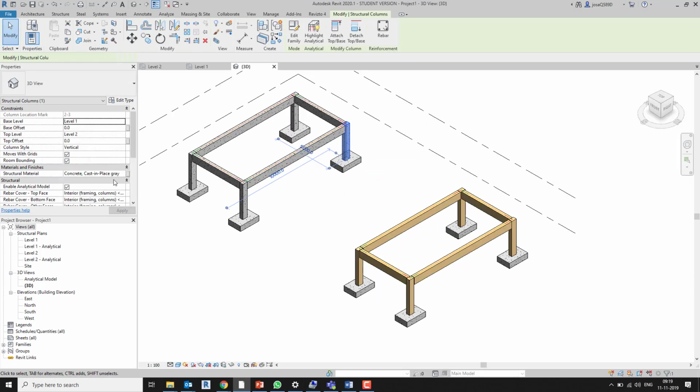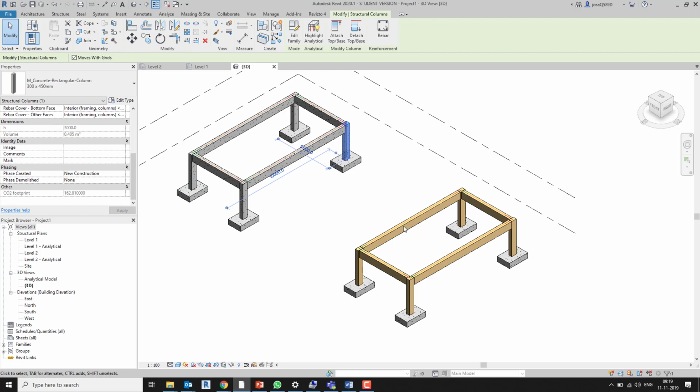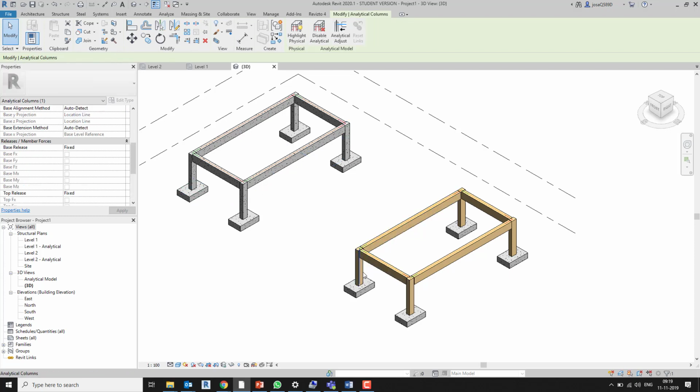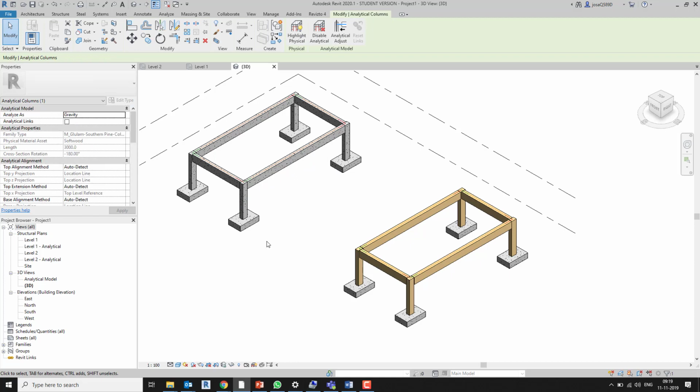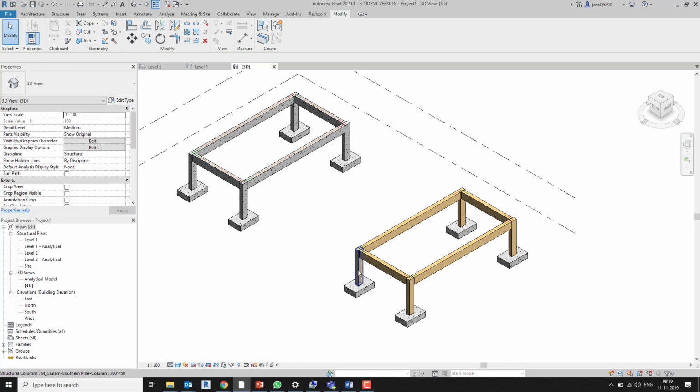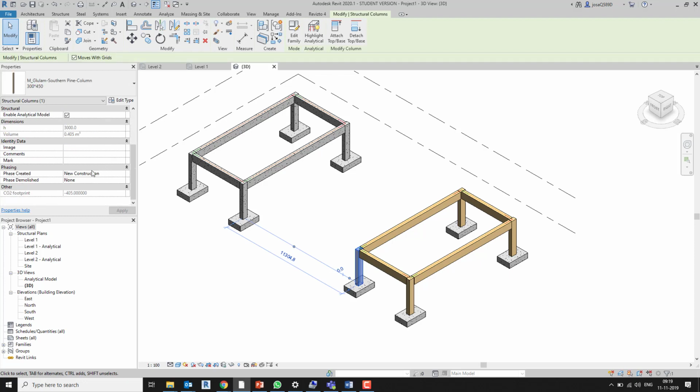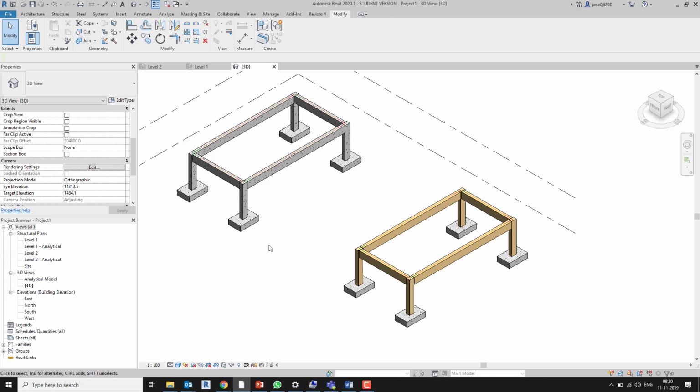Okay, so now if I come here, I should have a CO2 footprint of this element, so it's positive, and this one should be negative. No, it's not the analytical one. This one, yes. CO2 footprint minus 402. Okay, how much time do we have left? 40 minutes. I'm gonna do it, it's gonna be the same. It just changes because I'm gonna do it for beams and I'm gonna do it for foundations. It's gonna take a little bit, but it's gonna be the same.